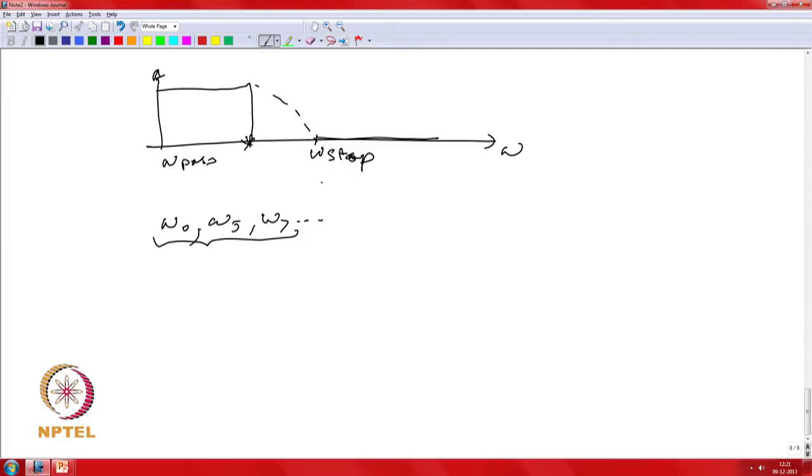Your stop band would correspond to your switching frequency, and its side bands and harmonics, and you are trying to ensure that all that is in the stop band, and then you could actually select your resonant frequency to be a geometric mean between your pass band and stop band.